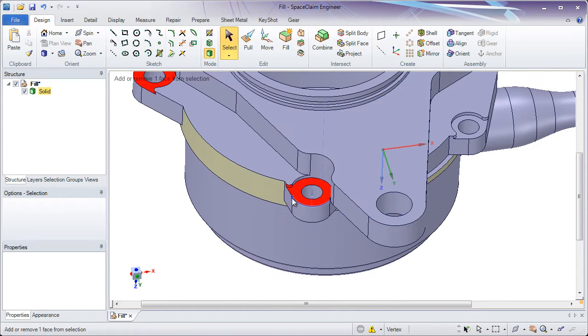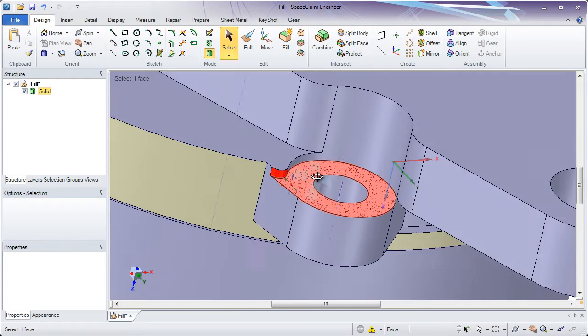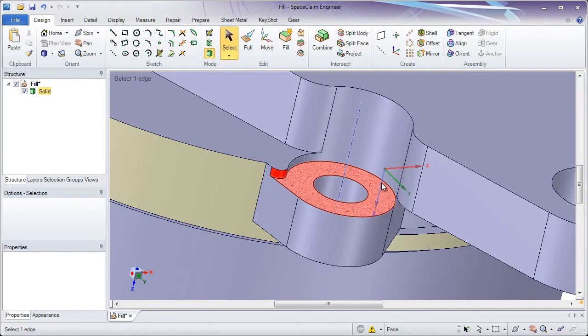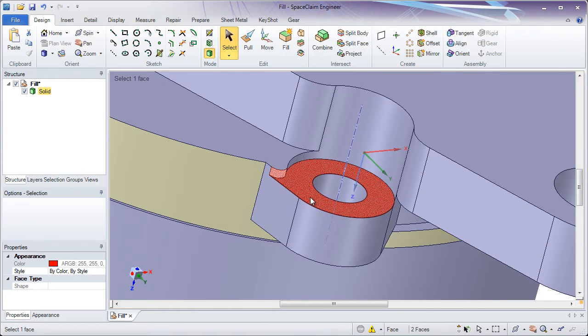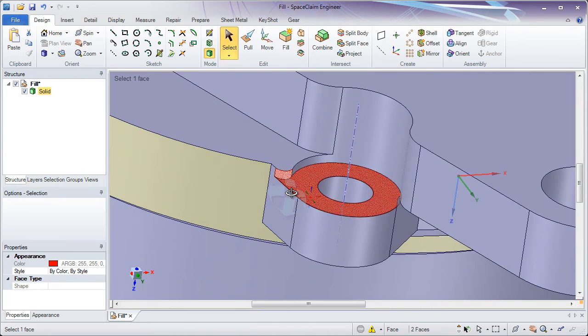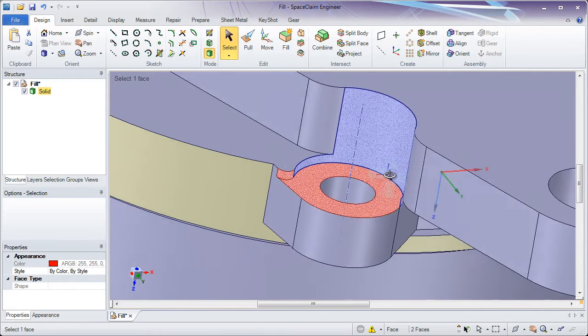Now the last example I want to show you are these red faces here. Let's say we wanted to remove this little small inlet here. You'll notice we box select them. We have the red faces selected. But now how is this going to extend to remove them? This face, I guess, will extend here and here to form a sharp. But this face will never extend up to this one. How is it supposed to know whether to extend this and to clip these faces here?